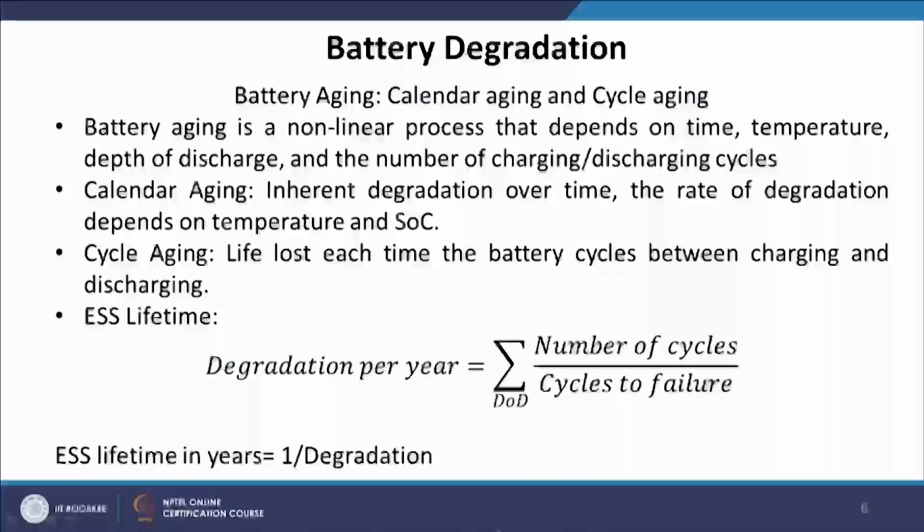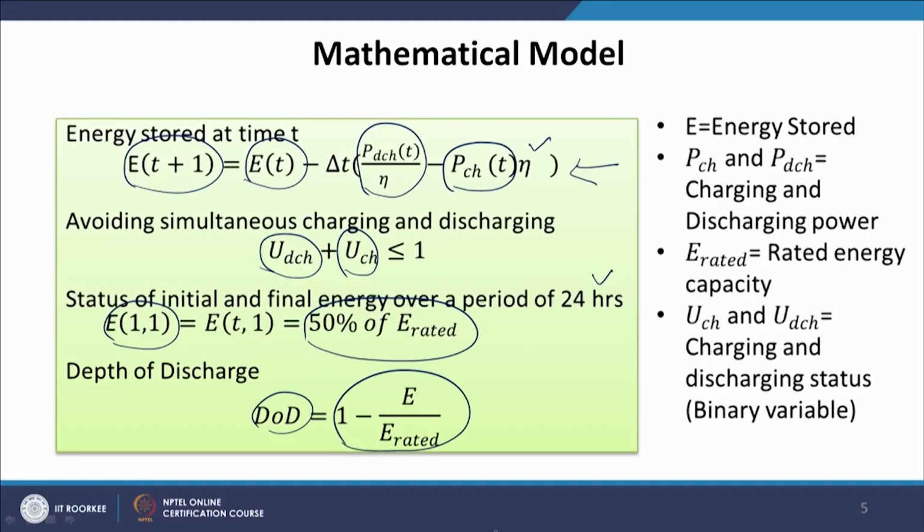It must be at 50% of its rated capacity, so its energy stored will be equal to 50% of its capacity. That is the theoretical assumption taken here. Do not get confused by the value 50%. At the beginning or end of the day, we are forcing the battery to hold a certain amount of energy instead of being completely discharged or completely charged, which is not acceptable. So, the ideal value could be 50%, which is what I wanted to highlight here.